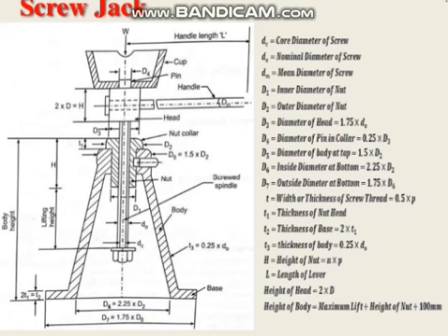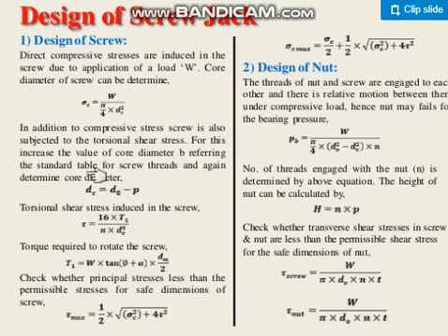Apart from that compressive stress, the screw is also subject to torsional and shear stresses. You see, now we are with the Tommy bar, we are rotating that head. When we are rotating, some torsion comes, so shear stress is induced because of that torsion.